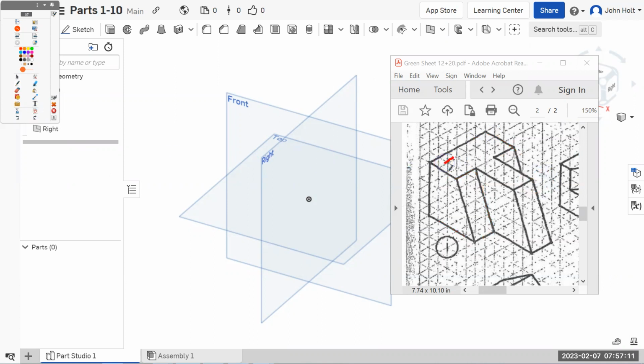And because they are the same, there's a couple of shortcuts to save you between 10 and 15 seconds of work. Anytime things are duplicated, there's probably a way to either pattern it or multiple extrusion or project the geometry and save you a few seconds. Okay, so we're going to start with this, make this huge long shape right there and extrude it.